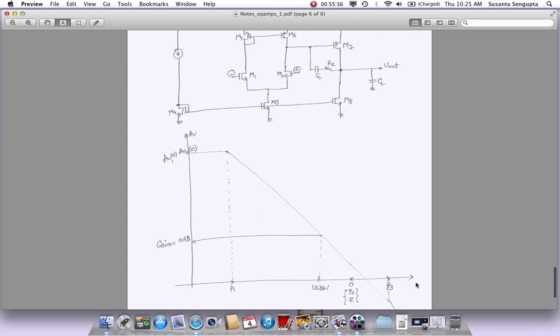So this is the Bode plot for magnitude. The low frequency gain being AV1 DC gain and AV2. So that's where the gain we get. We get the first pole as the dominant pole P1, where the gain starts to roll off at 20 dBs per decade. And hopefully, this CC has split the output pole far enough, where this is the output pole.